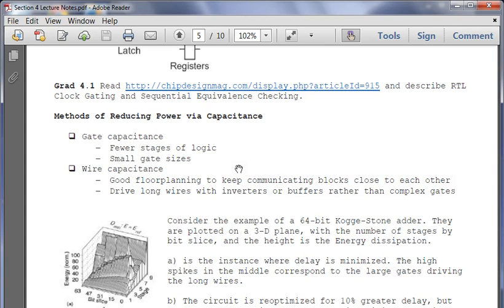So recall from section 1, you have your output pins and you have this plan, your cell block. If you have long wires between different portions of it, then you're actually going to consume more power. So you're going to want good planning with where your pins are. If you're given a cell and you only need this amount of area and you can actually use these 4 pins, you don't want to have something where half of it is over here and then have a long wire. This has a large wire capacitance. So good floor planning allows you to reduce power consumption.